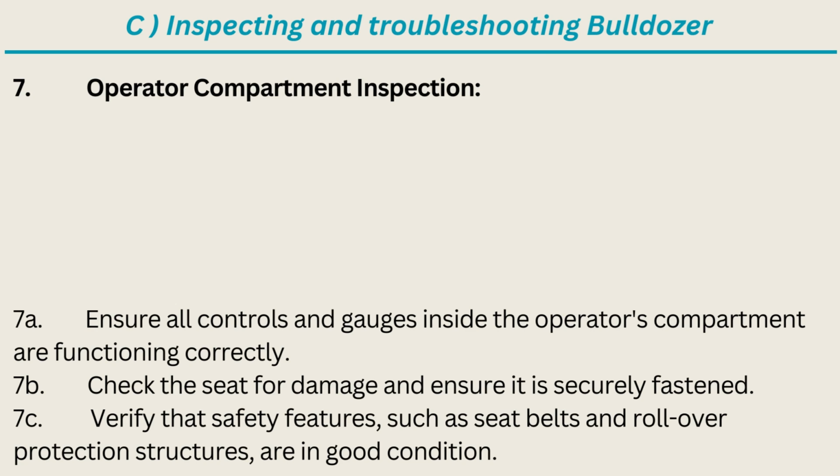7B. Check the seat for damage and ensure it is securely fastened. 7C. Verify that safety features, such as seat belts and rollover protection structures, are in good condition.